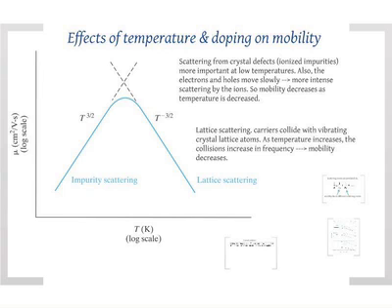Okay, so you see the effect is much more significant. Again, you see a drop in the mobility. What this says is that you have to be careful when you design a device. If you want a particular operating range of temperature, you need to account for this. And typically you want somewhere where the mobility is fairly constant. You don't want the mobility to be changing.